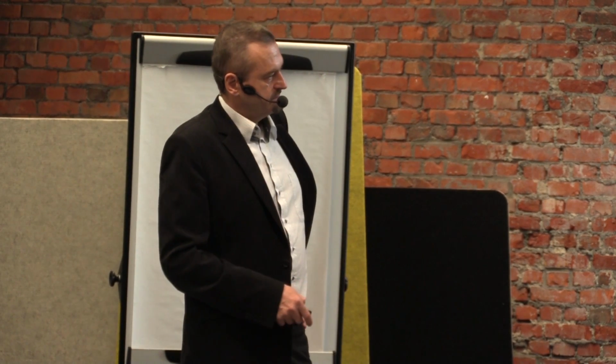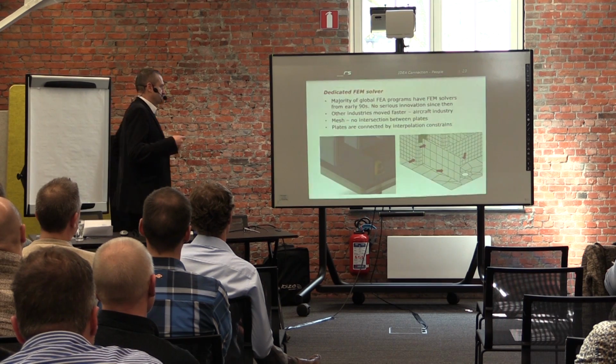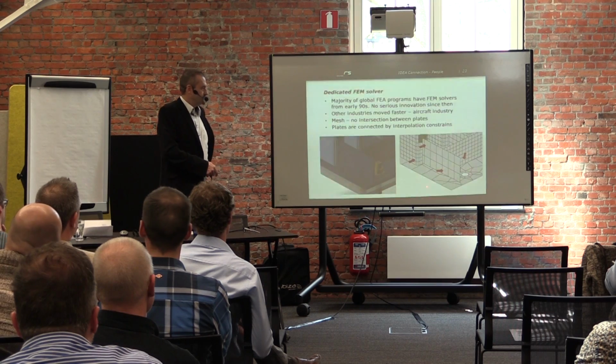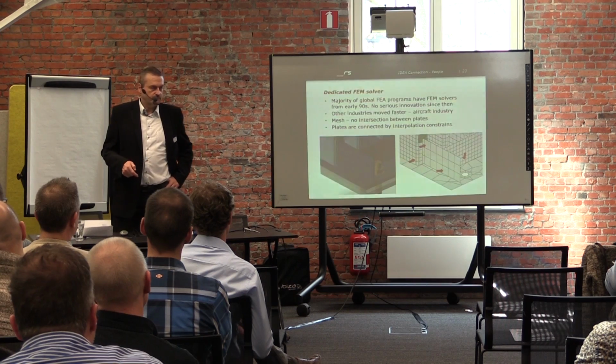It is very nice for this meshing. You see that this meshes, if it is rectangular, then there are only rectangular elements. But everything is properly connected, and the advantage is that we have proper or precise forces in all connectors. We have precise forces in all welds, precise forces in all bolts. And what is the side effect of this? When we do this, we have precise shapes of all plates, and we can use them for drawing.